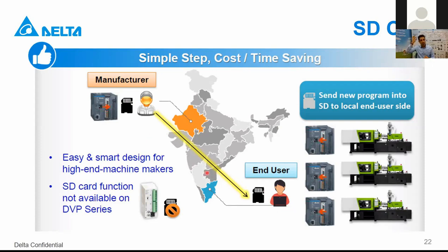Since it is not directly the same project, this is a kind of execution file. So they don't need to open ISPsoft or DIADesigner, and they don't need to know how to connect to the PLC. They just simply plug in the SD card and download to the PLC. So there is no need for any PLC knowledge for the end user. And also you can protect your user project, the source code, I mean.